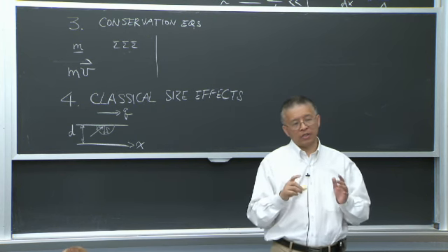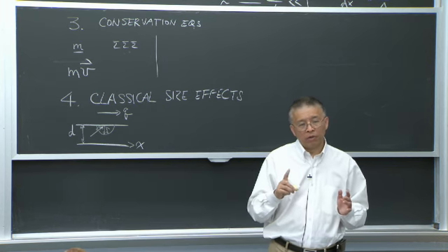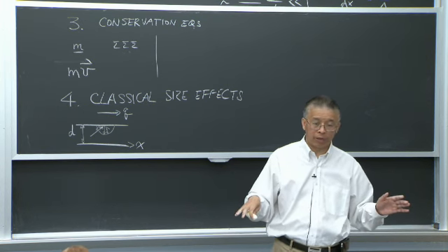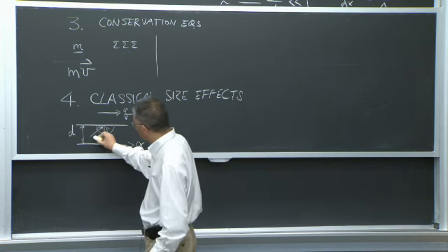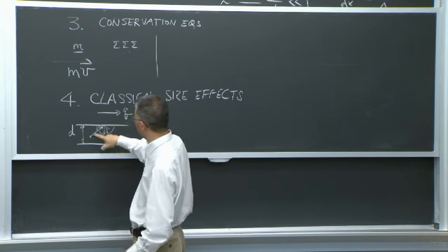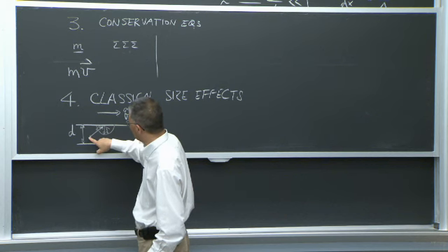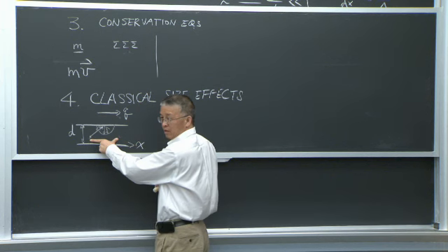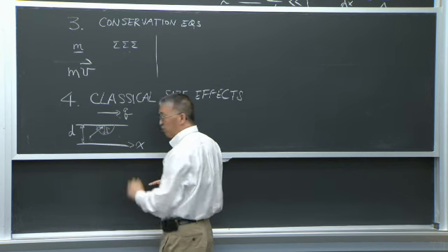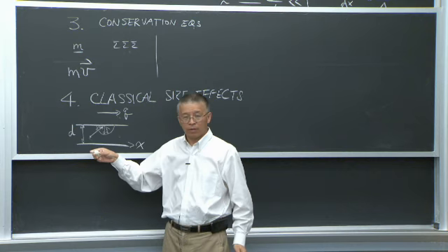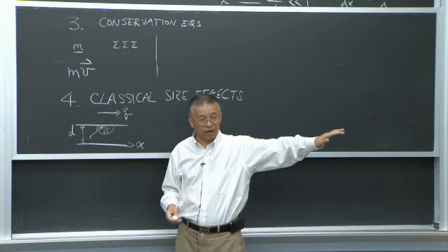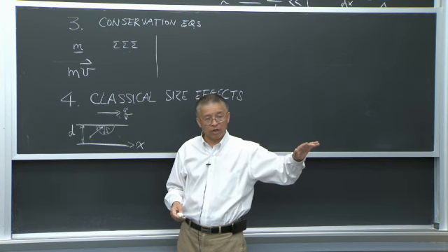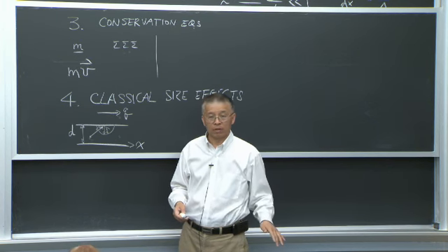In this case, conceptually, you'll have worse heat conduction than when you don't have the boundary. Otherwise, if this is the mean free path in the bulk material, heat will go from here to here, which means at least the distance in the x direction is this distance. But now, because of diffuse scattering at the boundary, half of them go back much earlier. So those kinds of size effects typically will impede your transport.